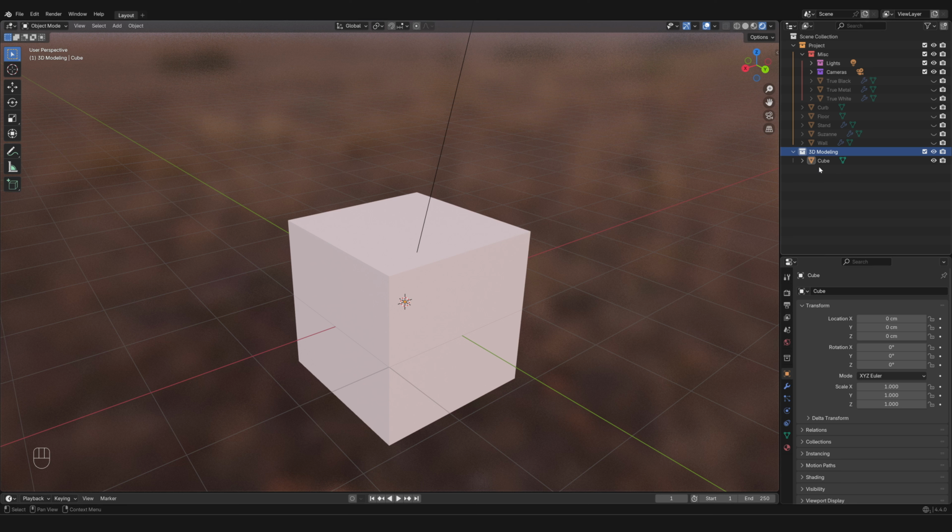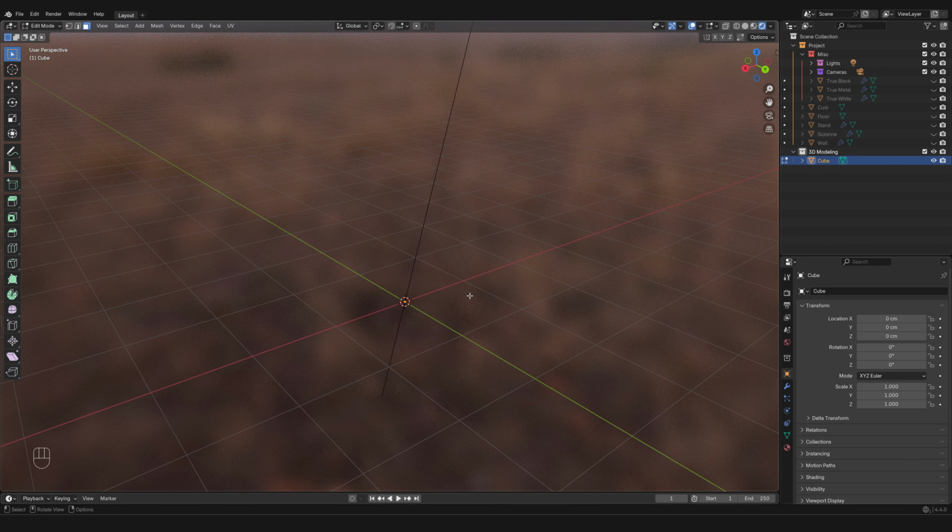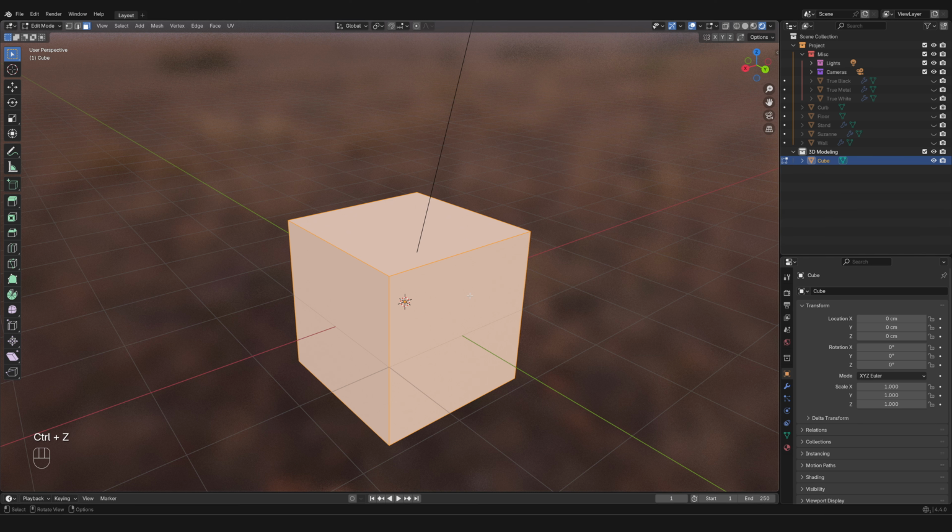In fact, although it might seem crazy at first, you could select the cube, go into edit mode, everything will be selected, just press X, faces, and now you have deleted everything in terms of geometry information inside the container, but the container is still there and it's still named Cube. It's not gonna rename itself, but technically now it's just an empty object. It's there, but there's nothing in it. This is important to understand because actually inside a container you can have any number of objects.